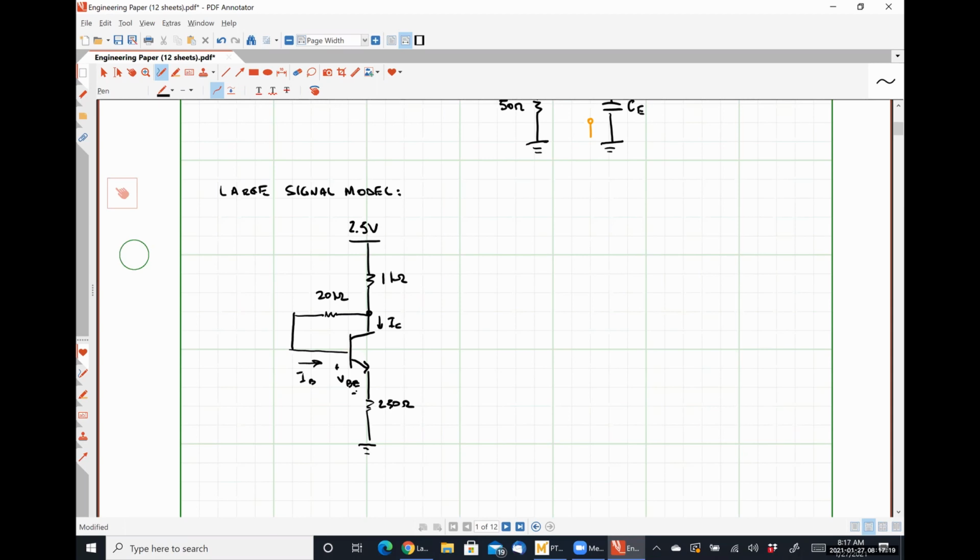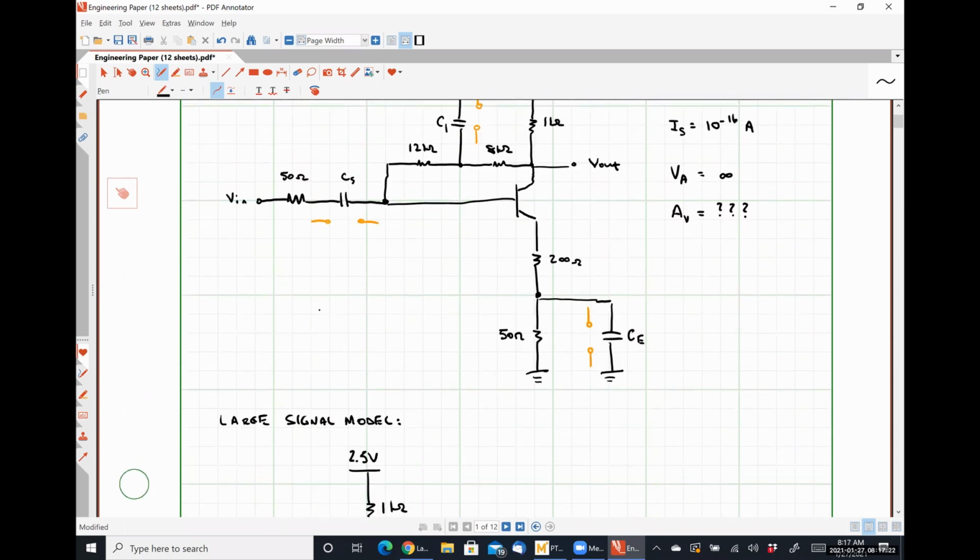Right. So when we open circuit that guy right there, that takes that guy out. Because the VN represents the small signal that we are trying to amplify, it's actually very good that we are disconnecting that, because that would be considered a short to ground, since we're effectively working this using superposition. So it will be turning off that VN voltage source.